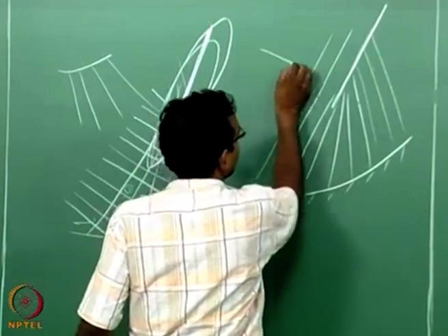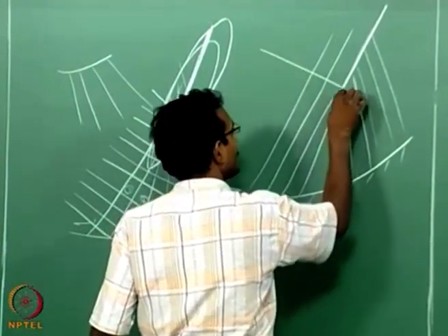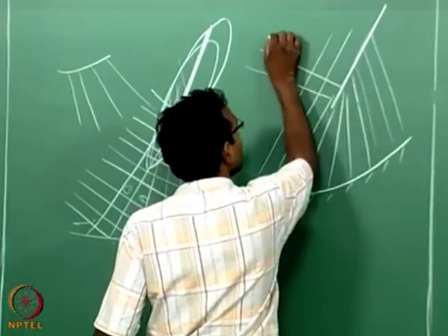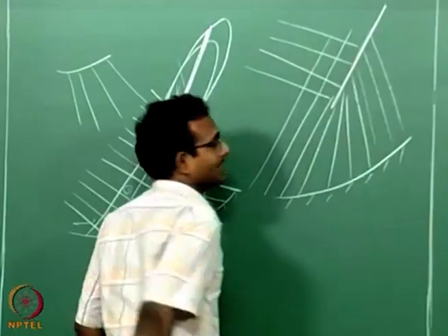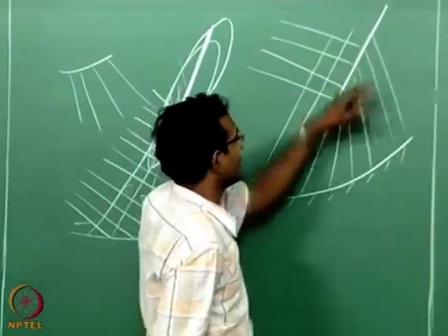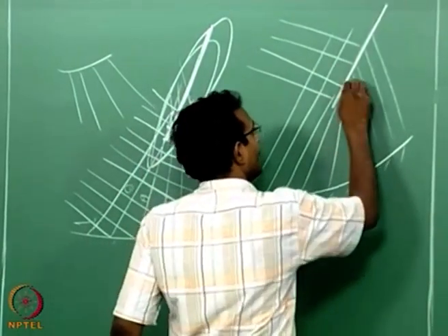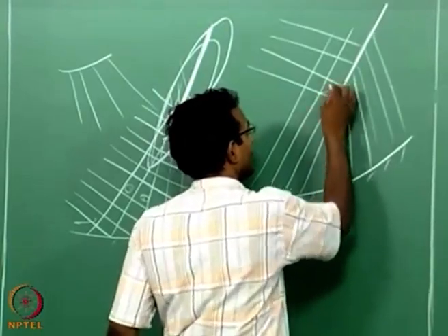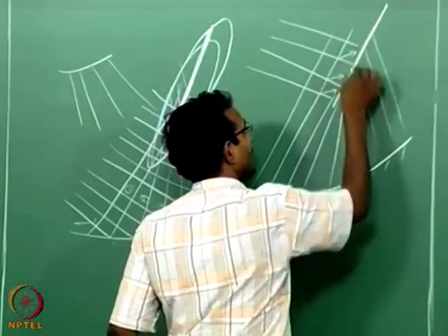Whatever points are coming this side are now supposed to go in a different pattern. This is the original pattern that it will see, and if you look at it, the velocity vector after this oblique shock, you know, is the angle bisector at any point on the characteristic mesh.